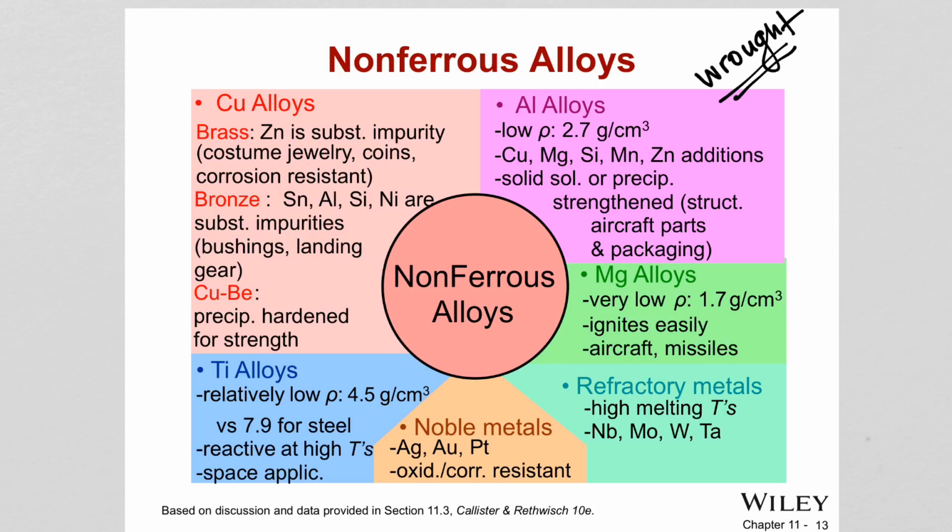So there is also another type, beryllium copper alloys. They have very high strength, excellent electrical and corrosion properties, and wear resistance. They are costly though, but they can be used in jet aircraft landing gear, bearings and bushings and springs, and surgical and dental instruments.